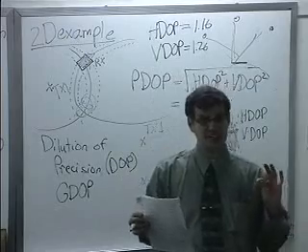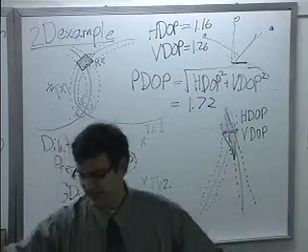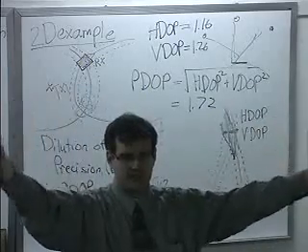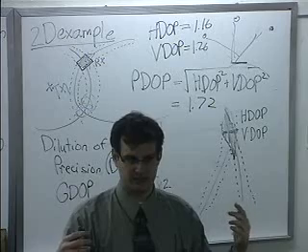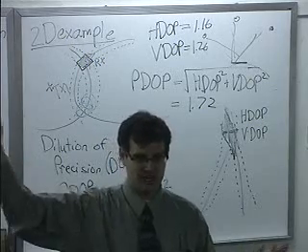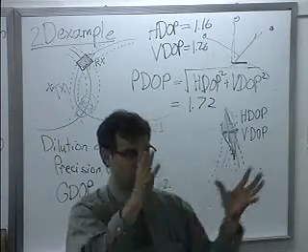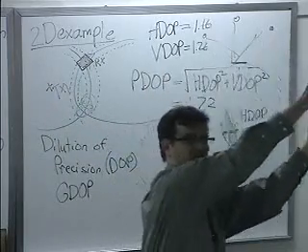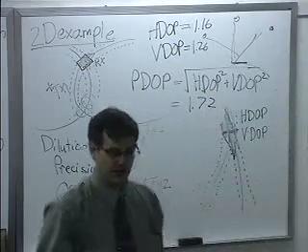Keep in mind that this is an average number. During the course of the day, the GPS satellites are zipping around. There may be a pathological situation where either because of the time of the day and the location you're at, or just because multipath or a mountainside is shielding you, that you might actually get some really bad PDOP, just because all the satellites that you can read are over in this part of the sky. And that's very terrible for any type of